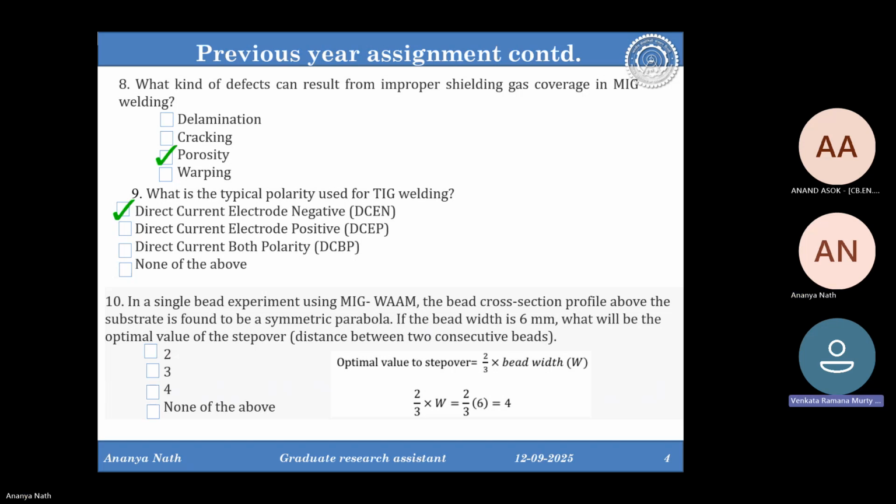Yeah, I have the solution for this. Even I opted for substrate, but I got clarity that in microcasting, the loop is actually between MIG and plasma. The work part need not be an electrode. We are not giving any connection to the work part. One connection, the positive, we are giving to MIG, and the negative we are giving to plasma. So plasma consists of a tungsten electrode, I think. So between MIG and plasma you have the arc generation.